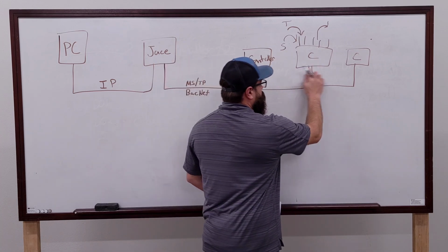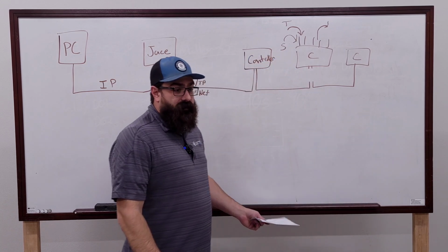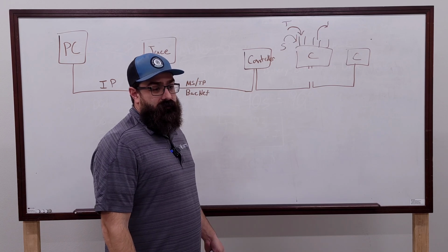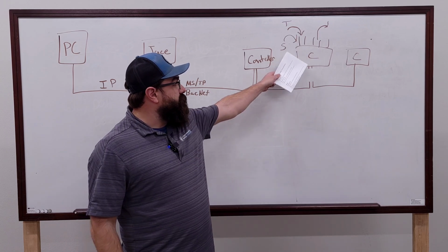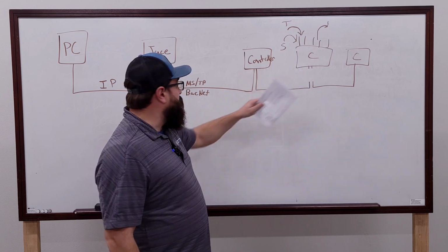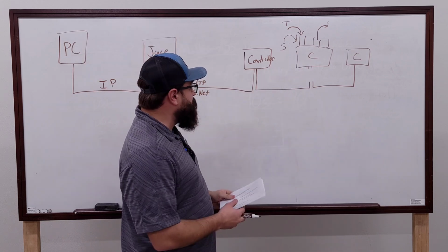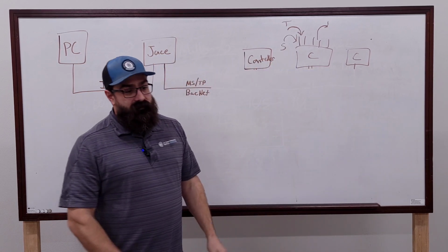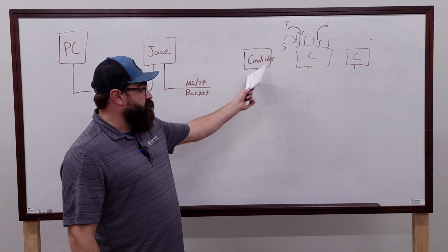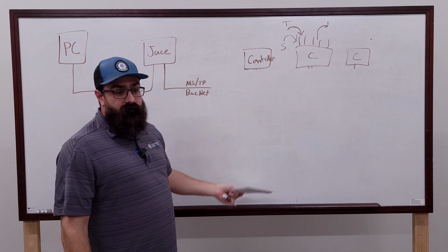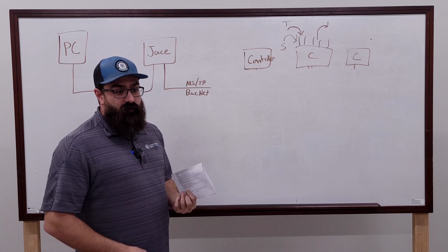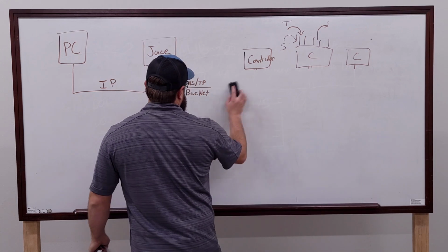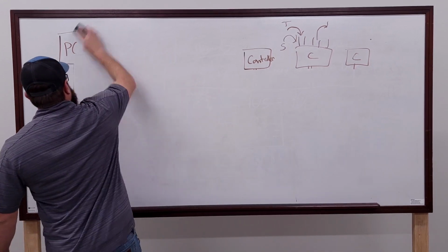Most of these will work without that there. They don't need it. They will default to occupied and they will default to a set point. All the logic to control their stuff is in them, not in here. So even if you were to completely wipe this out and do what we call a standalone system, where there's just a controller and a VAV box, they'll do their own thing. They have a temperature and a set point and they're set to occupied. So that's just a quick explanation.